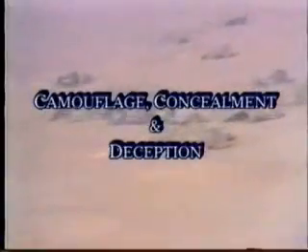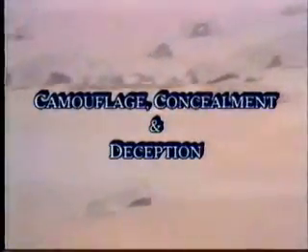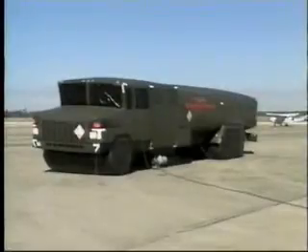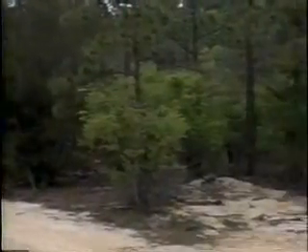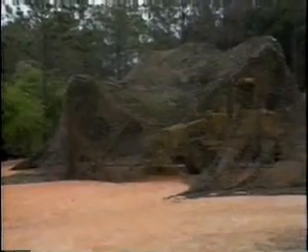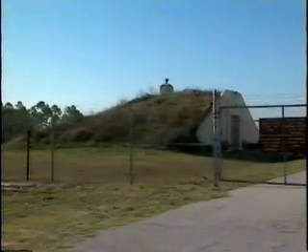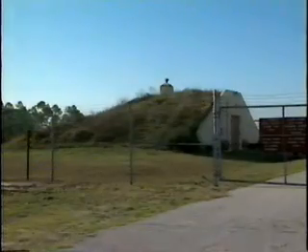Camouflage, concealment, and deception should be incorporated into wartime dispersal protective facility design and siting, as well as into vehicle and equipment dispersal locations. Pre-planning for dispersal locations should include using wooded areas or elevation changes that blend facility and vehicle contours into the surrounding terrain, or facilities where earth and grass coverings are used for hardening when possible.